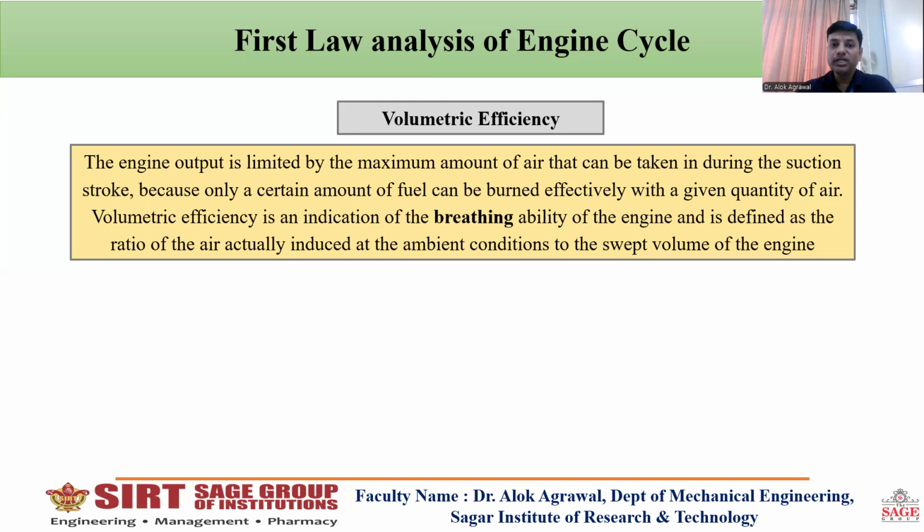Volumetric efficiency is also an indication of the breathing ability of the engine, where the maximum amount of charge that can be taken inside the combustion chamber is its swept volume. When the piston moves from top dead center to bottom dead center, the maximum volume swept is the swept volume, and that is the maximum volume of charge that an engine can take. But actually, it will not take that amount.